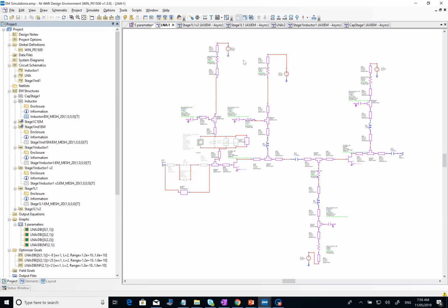But if you're brave enough, you might go ahead and do an EM for each stage, and it might work, it might not work. I think if you don't get the inductors at least right, it won't really work. If you don't have it meeting the specs perfectly but it is close enough, that's okay for review 3. Or it at least has certain gain, like maybe it's detuned, but that's still okay for review 3. Obviously it's best if you meet the spec, but if you don't, that's fine.